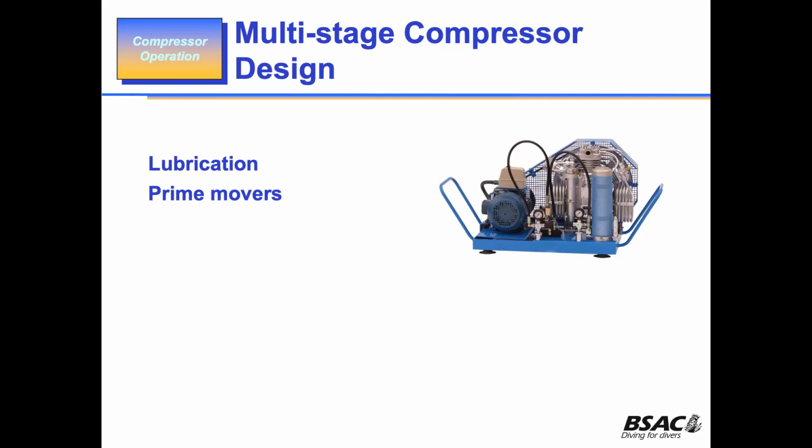You have one big pole that takes in your air from a high point, and you try never to locate the compressor with the exhaust upwind of the inlet. Turn it around the other way, so if any wind is blowing, it's going to blow the exhaust away from where you're sucking in the air. So those are the prime movers that you'll use: small petrol engines like a Honda, single phase or 3-phase electric motors.